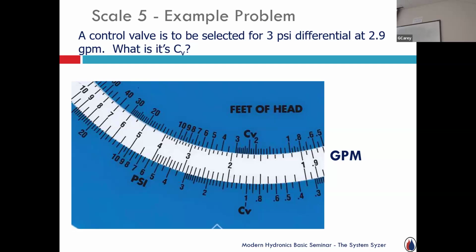So a 2-inch pipe, steam, water, whatever, flowing through a makeup air coil, heat exchanger, whatever. And now I've got a valve that can handle a hell of a lot more than what I'm actually moving through this 2-inch pipe. So a lot of times when you look at control valves, you might see a 2-inch pipe get throttled down to say 1.25 inches, and then blow back up to 2-inch, because I need the 2-inch for the flow, but I want the valve authority, the control.